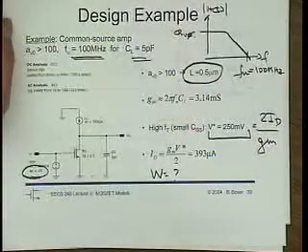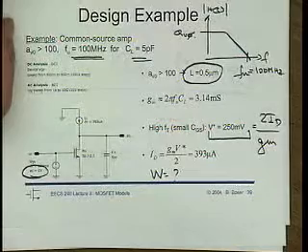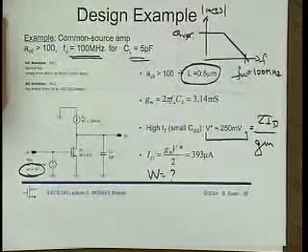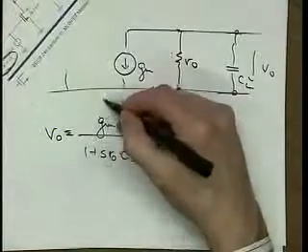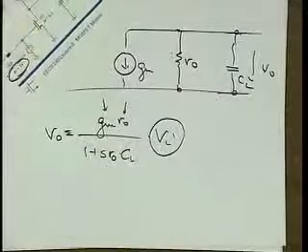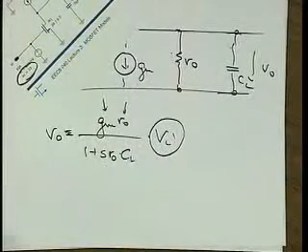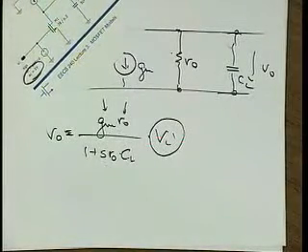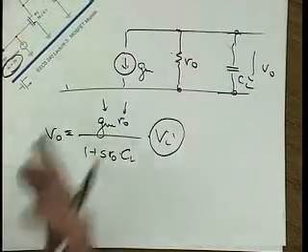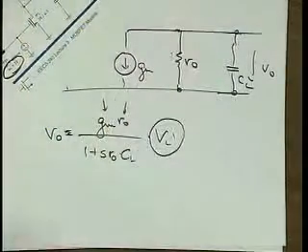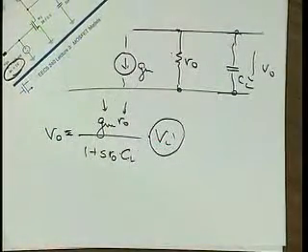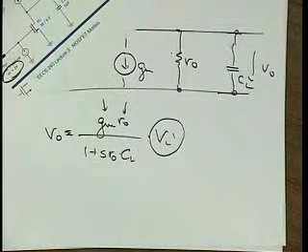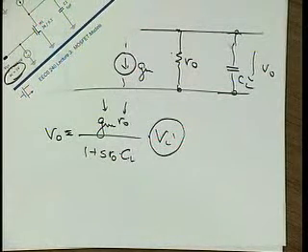That one you need to be accurate. That's a physical real voltage, because that one is what SPICE is going to use to figure out what gm and ro and all of these things are, right? And of course, if you bias off, then it doesn't work right. But once you are in the AC analysis, that's no longer an issue. So we can safely use a 1 volt there.